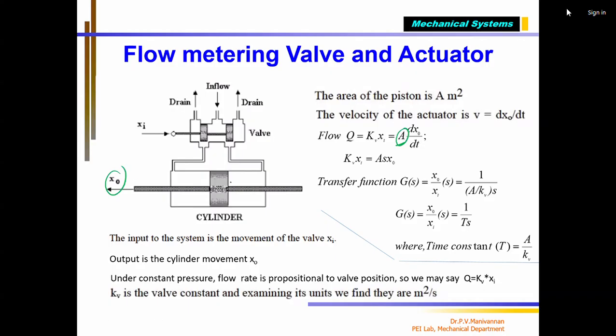I want to control the force generated, and that force is proportional to the area of the piston. Correct? I can optimize what the area is without actually making the cylinder itself. If you are designing the system, you can do this for each and every component. Correct? All this can be optimized using mathematical modeling without building the actual system.